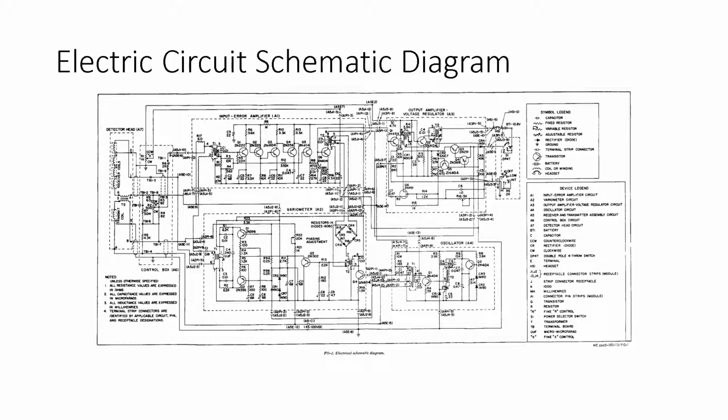So if we're looking at the R6 right there, it says R6, 56 kilo ohms from what I can see from here. My eyes aren't so good. But if you're looking at the 56 kilo ohms, we've not specified exactly which brand of resistor, or actually the wattage hasn't been specified either. So a parts engineer will go back through and kind of add some of that information in as we go.